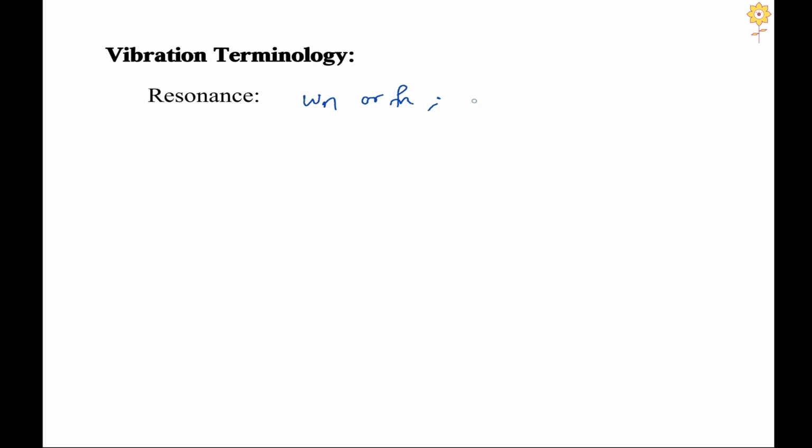So, I am having mass and stiffness characteristics of the system, and later you will see that to find this omega n we will be requiring the values of spring and mass characteristics. So, once they are designed, the value of this omega n will be practically constant. So, there will be no change during the operation of the particular machine or the system.